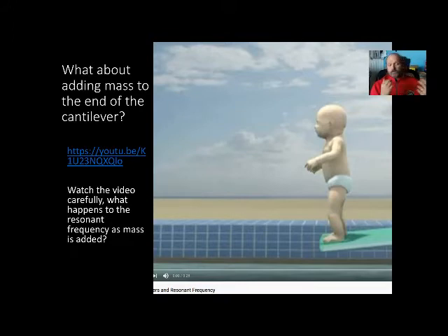So what you do is you create a cantilever and you add different amounts of mass to it, and then you plot the frequency versus mass added to your cantilever. And then when you have an unknown mass added to the cantilever, you can determine from the resonant frequency shift how much mass you added.